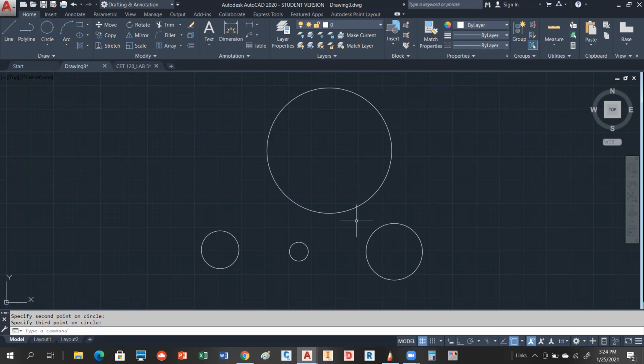A lot of times I would use it if we were locating a big tank, like those big tanks along the river where they store gas or petroleum products. We would have to sometimes locate the center of those tanks, and you're obviously not going to be able to climb down in them and get a center point. So we would locate 3 points along the tank somewhere, and we could calculate the center by doing that. It's a really, really powerful option.